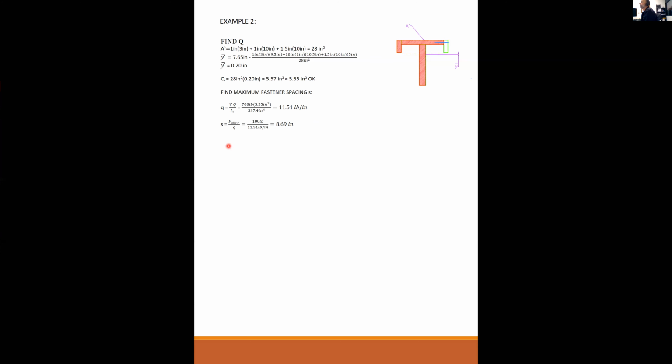Yeah, F allowable was given by the problem statement at the beginning of the problem. Yep. And Nicholas, the nail is in the side. Yes, just like I showed here, the blue nail is what we're talking about, and the spacing of the nails is in the direction in and out of the page. So that's along this little side plane right there.